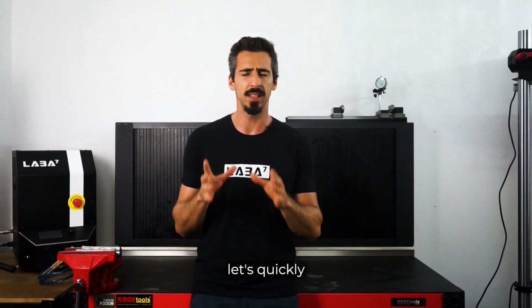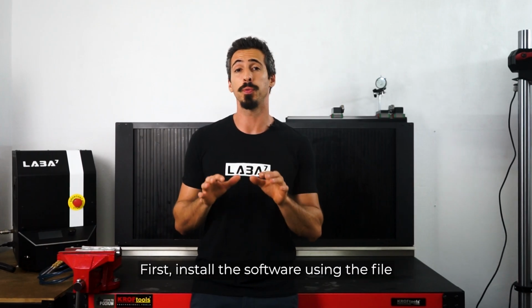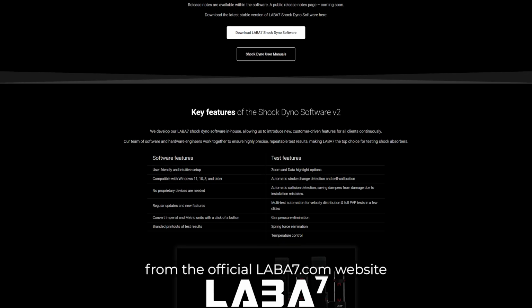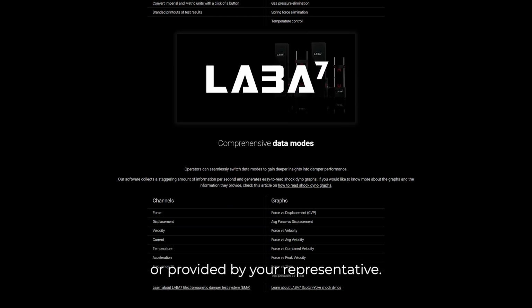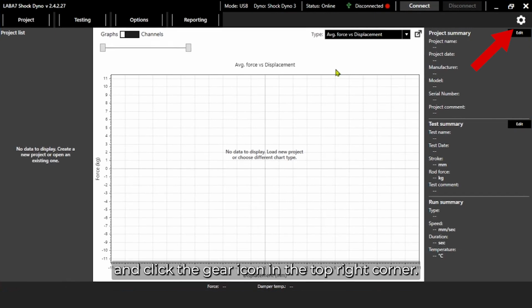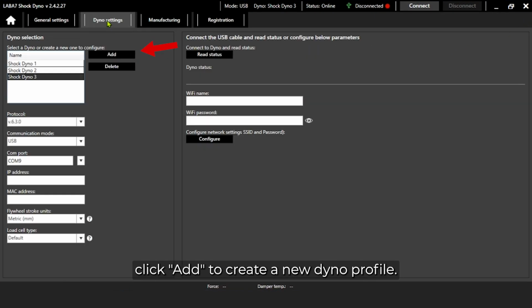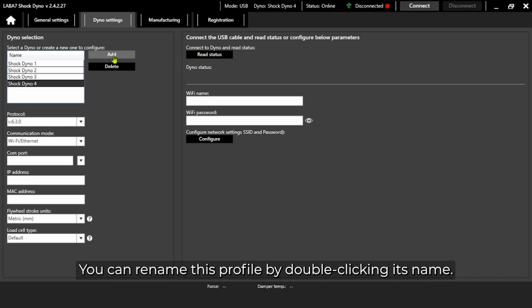Before you start testing, let's quickly set up your Laba 7 Shock Dyno software. First, install the software using the file from the official Laba 7 website or provided by your representative. After installation, launch the application and click the gear icon in the top right corner. Under the Dyno Settings tab, click Add to create a new Dyno profile. You can rename this profile by double-clicking its name.